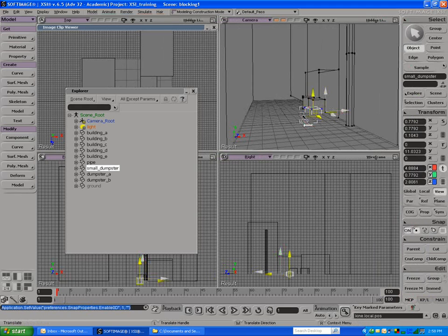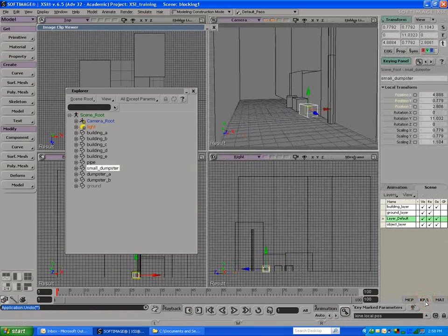You will still be able to snap to the ground, you just won't be able to select it. So that's quite useful. Again, this would be similar in Maya to reference mode, or template, reference, not templated.